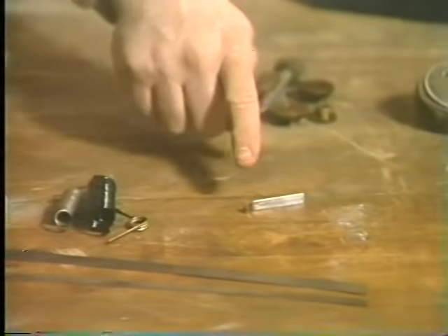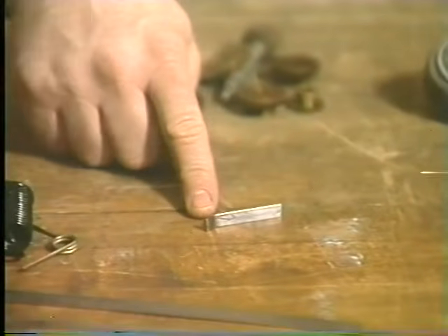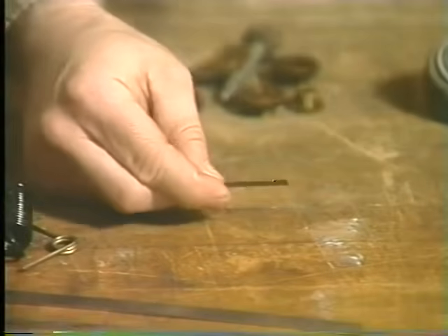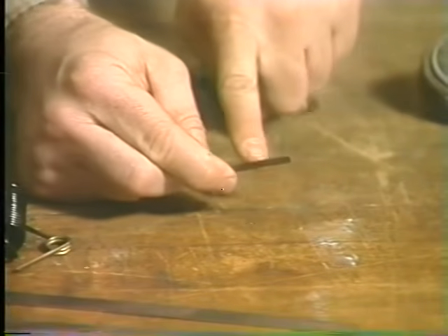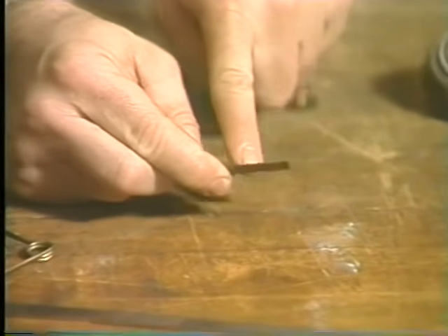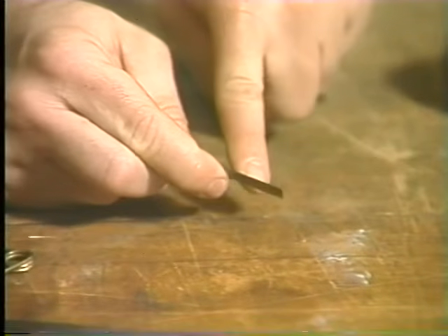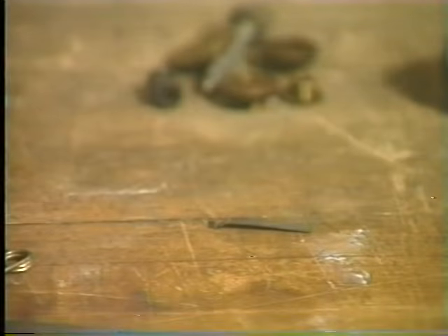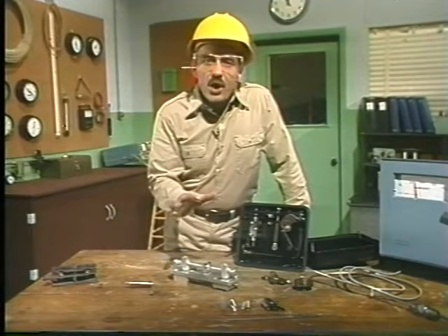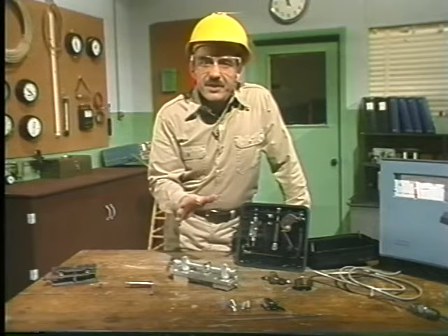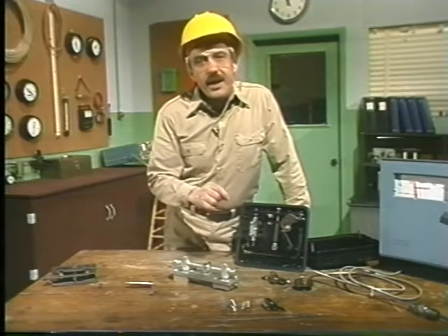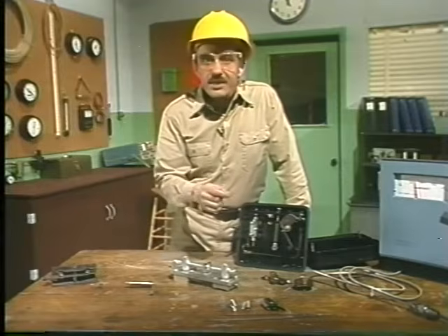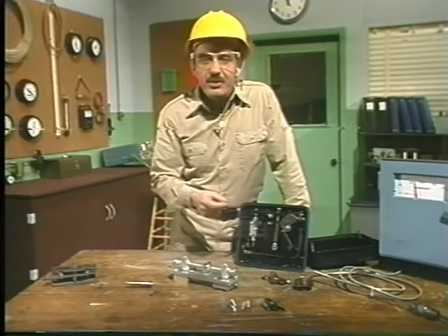Straight springs are typically fixed at one end. When a known force is applied to the spring, it will move or deflect a specific distance. And every time the same force is applied, the spring will move the same distance. When the force is removed, the spring returns to its original shape. Generally speaking, long straight springs will deflect a greater distance than shorter ones, and thinner springs are typically more flexible than thicker springs of the same material.